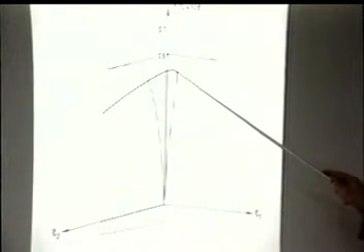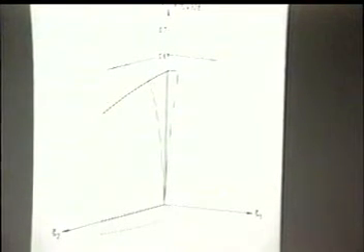But you are interested in where the limit point is, right? Because you calculated the B factors for the structure and you have inputted a certain imperfection. So you want to know what its effect is. And essentially, as I said, to perform this operation, even on a PC, takes maybe 2 seconds. It's a very quick operation. You don't notice it practically.